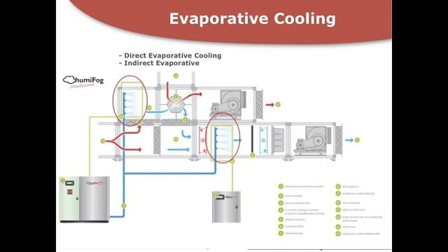The air handling unit software controls these cooling devices by enabling them to operate if the system is within working limits and if there are enthalpic conditions, and will run them in sequence depending on the cooling demand, from the most efficient to the least efficient.